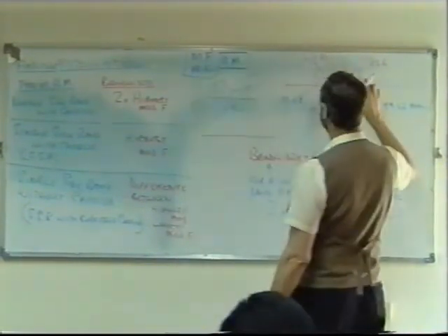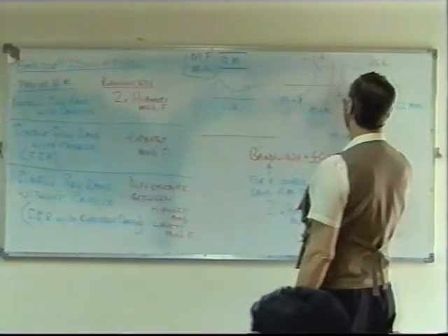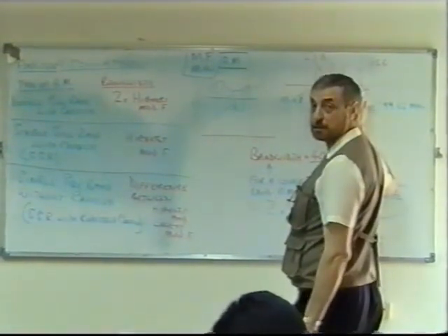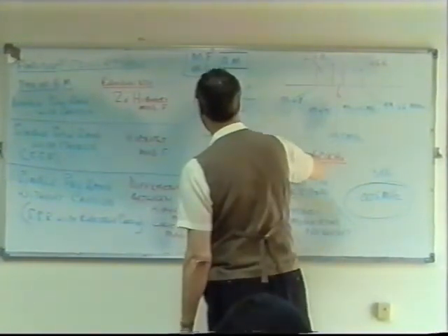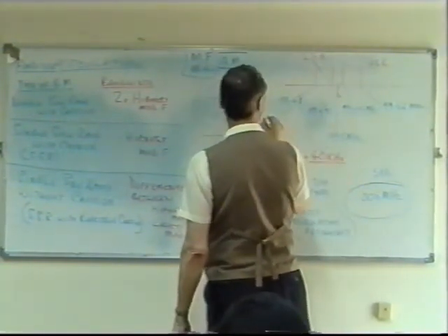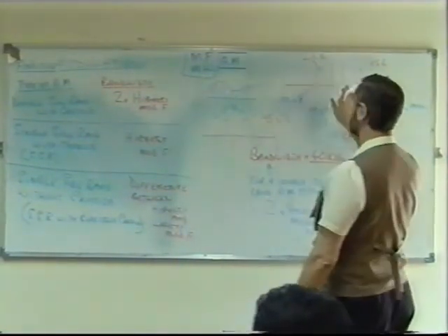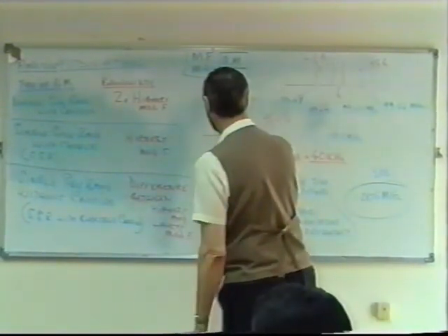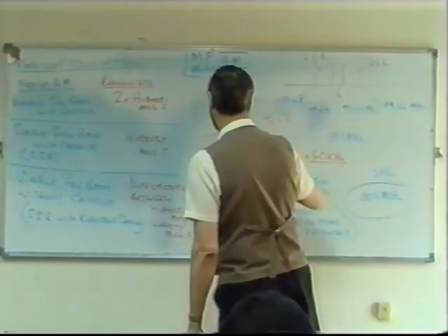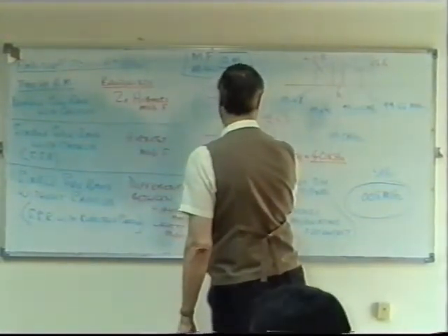If I transmit, for instance, an upper frequency, let's say 20 kilohertz modulated, then it will be a single sine wave, and that single sine wave will be 99.52 megahertz. If I transmit the lower frequency, 5 kilohertz, it'll be another single sine wave, and again another radio frequency of 99.505.